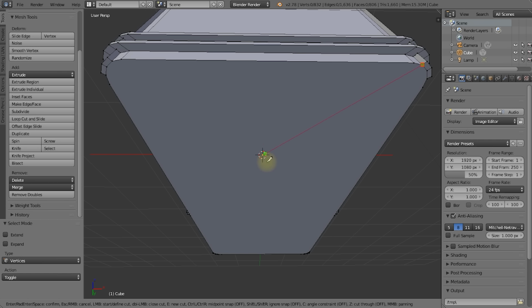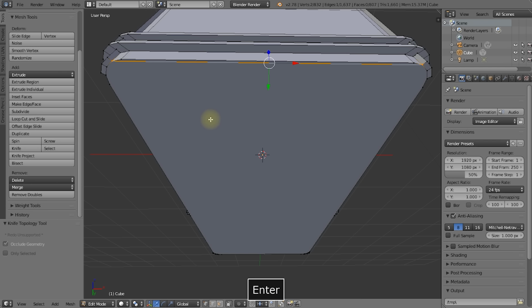This is going to create a cutting line, and let's connect that to the exact matching vertex on the left side of the mesh. Click and then press enter to cut it. And now we've essentially turned this top piece here into a quad. Now this face down here is still an n-gon because it still has way too many vertices. So let's just keep cutting.